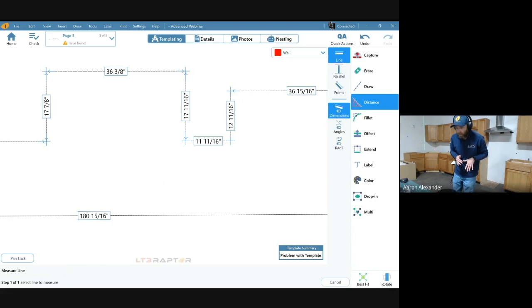Yeah, sometimes with the crooked wavy walls that previously had old backsplash, it's hard to determine where to shoot the points because the wall isn't flat and straight. Right, exactly, Jimmy, right? So this is where we can take that scribe, we can shoot those points to see what's going on there, right? When we do the countertop, so when we do a horizontal plane and scribe that back wall, that's giving you your bird's eye view down to see what that wall's doing. And where the proudest parts are, you know that's the part that's going to affect your backsplash, right? So we can use the wall scribe of our countertop to kind of see how flat the wall is, right?